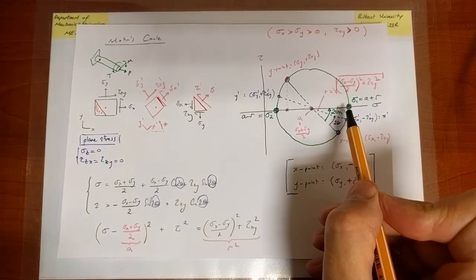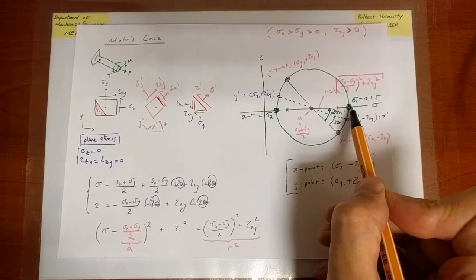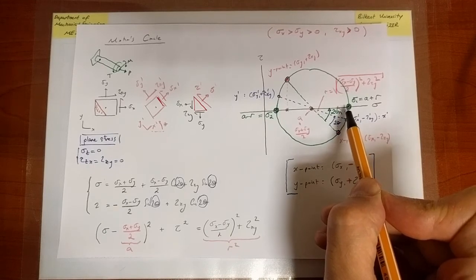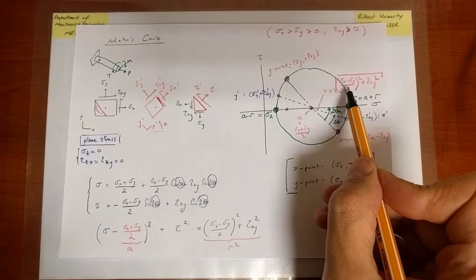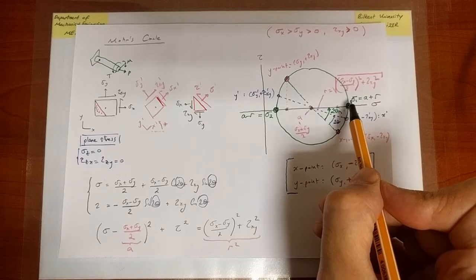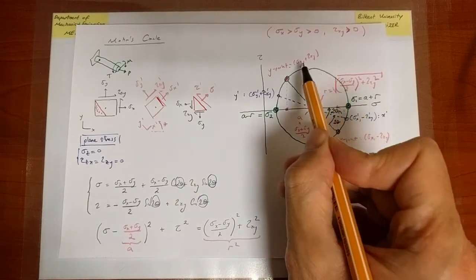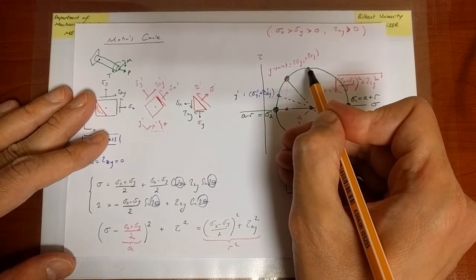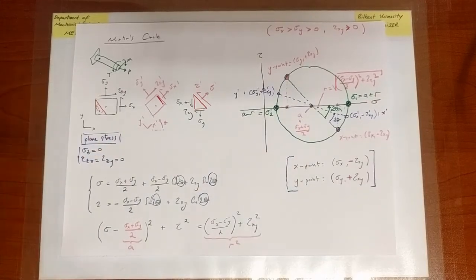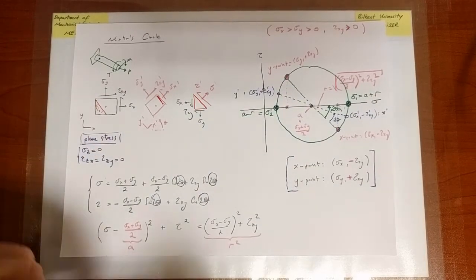Now, once you reach 2 theta n, the principal plane, if I rotate through an angle of pi over 4, I know that I reach the plane with maximum shear stress, the principal shear stress plane. And on the Mohr circle, I rotate twice as much, so that's going to be a rotation of 90 degrees, not 45, to reach max shear stress or principal shear stress, but twice as much on the Mohr circle, and therefore the rotation is going to take me up here, and indeed you see that the shear stress has become a maximum. And at that point, let's now plot that in some other color, let's say black.